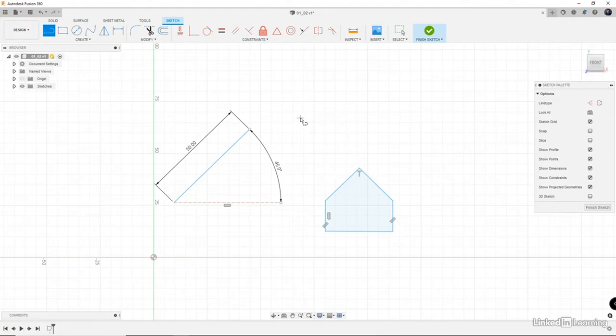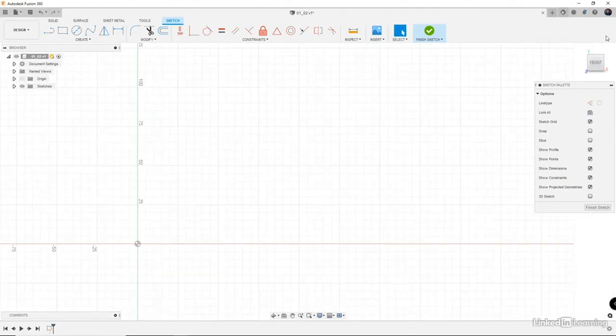Now we can also select a point, draw a line, end it someplace, and we can hit the check mark here, which will keep us in the line tool itself, or we can select someplace and then hit enter, and we actually leave the line tool at that point. So if we wanted to go back and use the line tool again, we'd simply hit L, and we're back in the line tool. Now let's talk about rectangles.